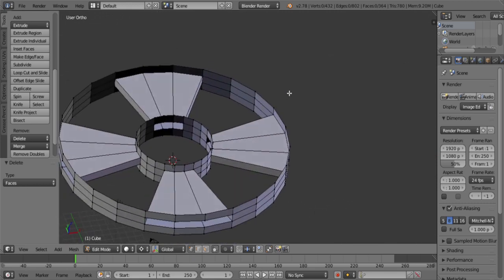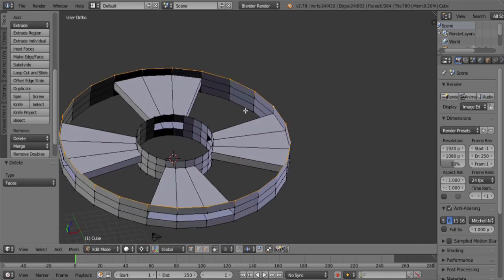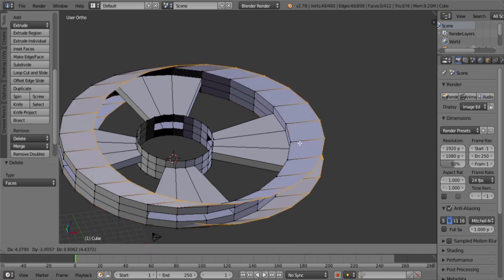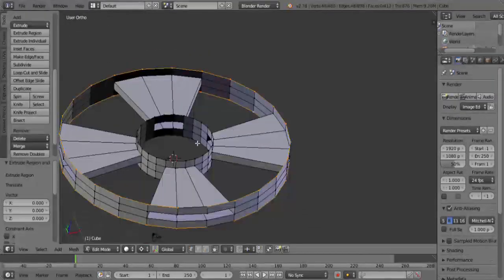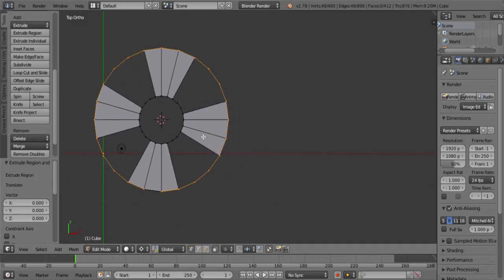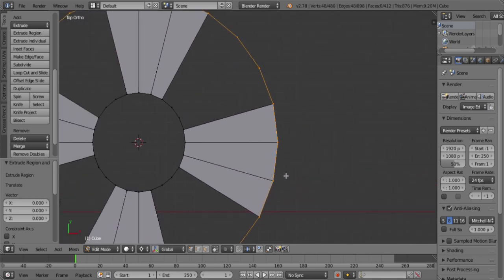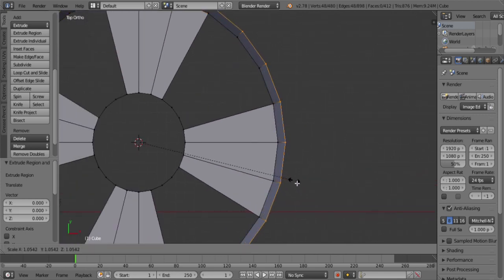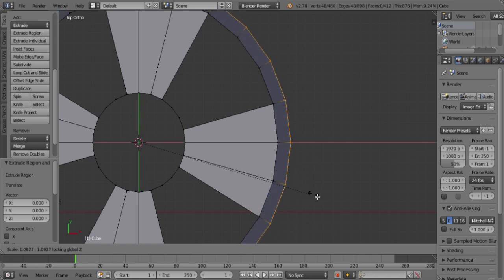And now I'm going to use another trick. I'm going to extrude these two. Extrude. Right click. And now I'm going to scale it in 1 step. Now how can I do that? Scale, I can just try and do it like this, but it's Shift C. That's difficult. I'm going to use a calculation. The outer ring is 30, and if I want to extrude this 1, I have to use 32.